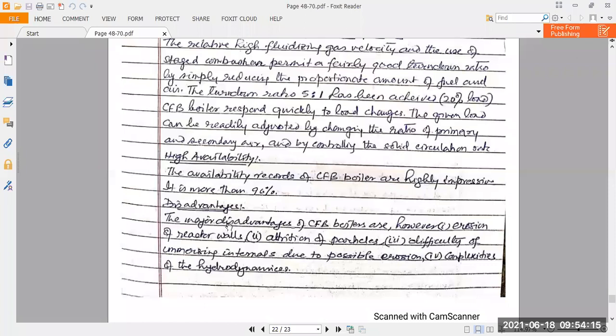So what we have? The supercritical once-through boiler is the only type suitable for supercritical pressure. Once-through means the water goes through totally. There is no number of stages because there is no latent heat of vaporization. It does not require vaporizing in the coil; the water is already vaporized. The water, on being heated at constant supercritical pressure, suddenly passes into vapor, and there is no saturation temperature as such.